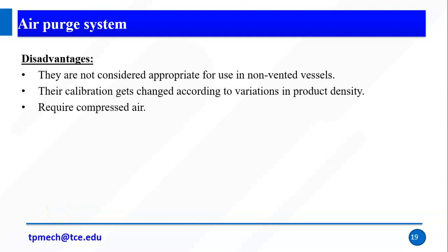The disadvantages: again, it is not used for non-vented vessels. We can measure, but it is not considered because of some limitations. Their calibration gets changed according to the variation in product density. So as I said, we can use it for some dirty water level.